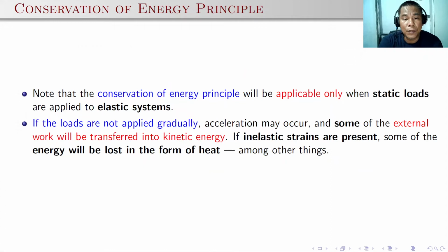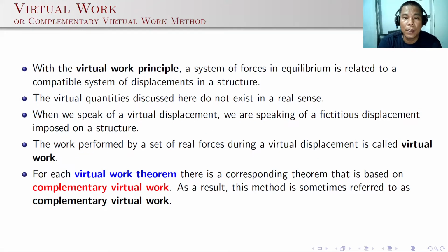Note that the conservation of energy principle will be applicable only when static loads are applied to elastic systems. If the loads are not applied gradually, acceleration may occur and some of the external load will be transferred into kinetic energy. If inelastic strains are present, some of the energy will be lost in the form of heat, among other things.